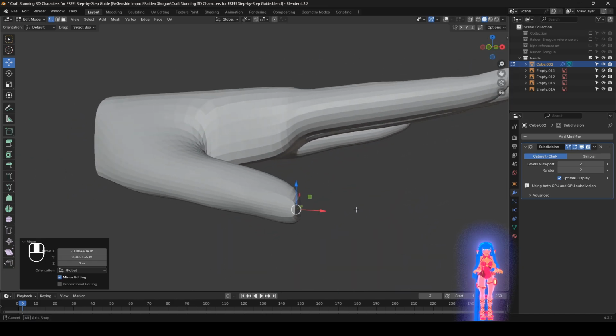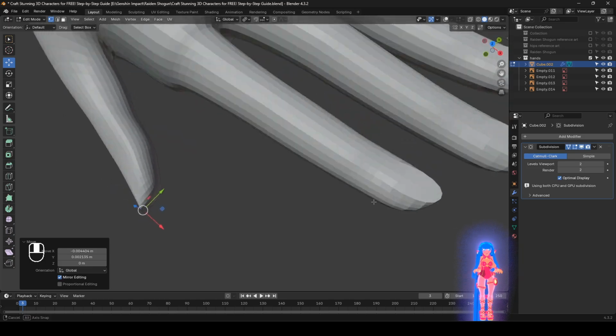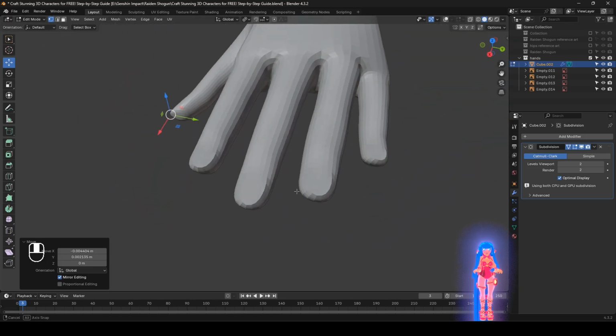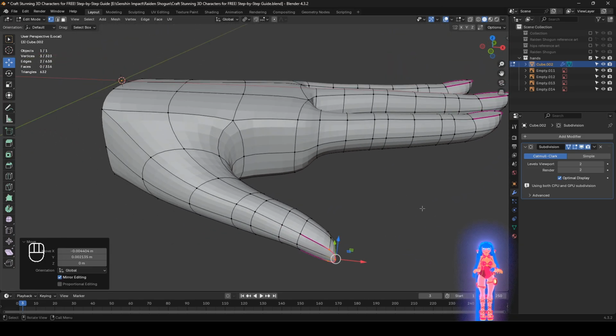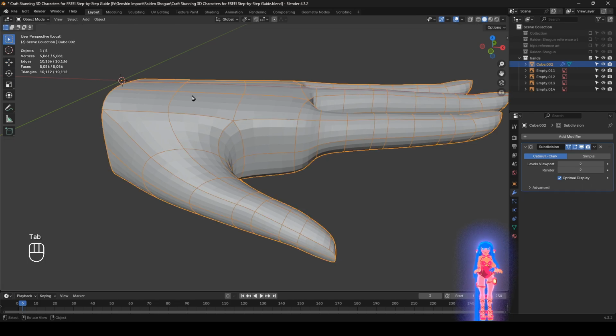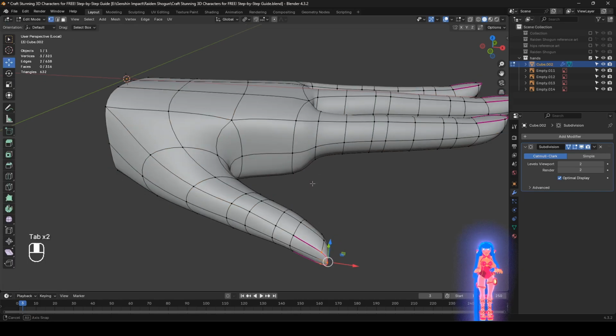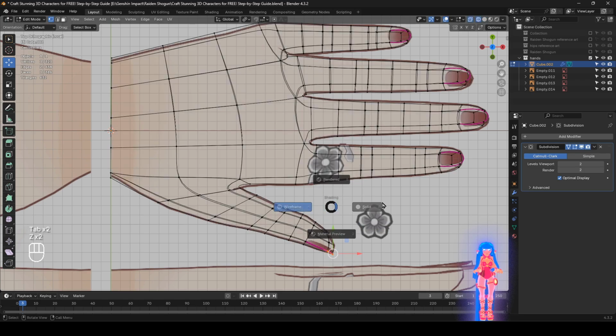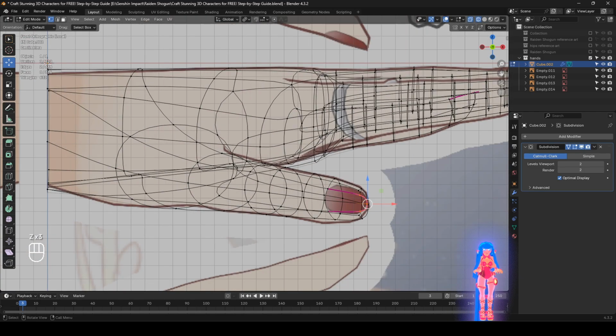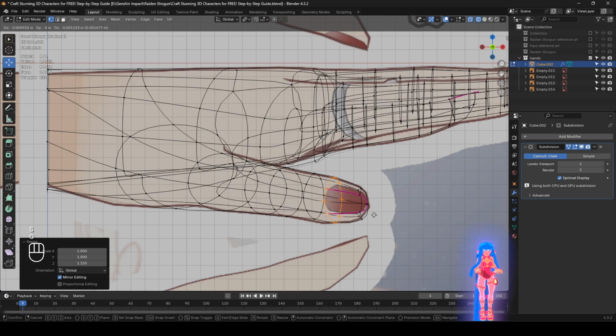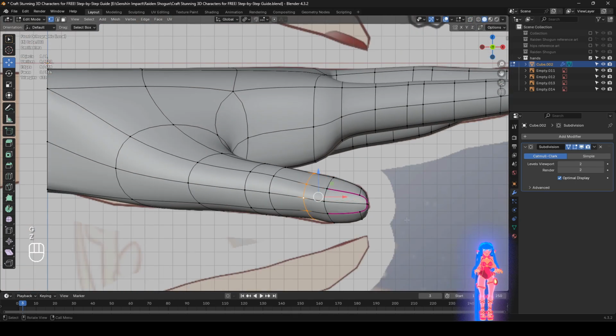We are so limited on topology. Only the thumb looks good, and the rest of it probably looks okay to you. All right, go into Tab, right click, shade smooth, then go back in. And now we basically have the thumb formed. S, Z, and...